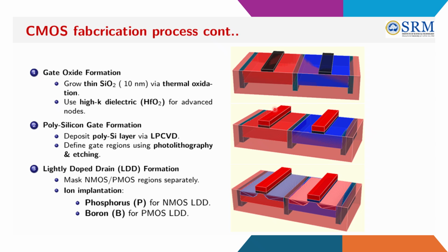Now if you want to develop the polysilicon layer, that is exactly the gate material, after the oxidation process, oxidation meaning the SiO2 layer, then to develop the silicon layer over this SiO2, how will we do it? We can use LPCVD, the chemical vapor deposition technique. So a deposition technique will be used. Here again you can use photolithography and then the etching technique. Suppose the height is higher than the width, or whatever, you can use the etching technique after the deposition. Okay, so here is the deposition technique.